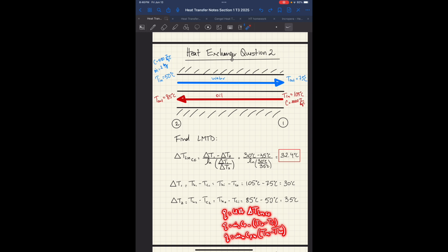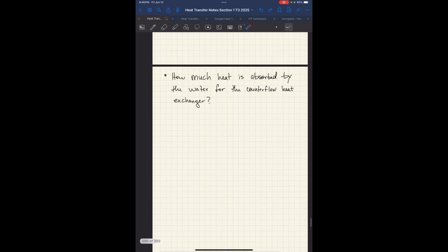One of these three equations. Any of them would work. Now, the idea is that in this particular question, only one of those equations will work because you only have information for that one. So basically, the only equation that'll work is the m dot equation for the cold fluid. So you can go ahead and do that, plug in your values, and you get your Q.